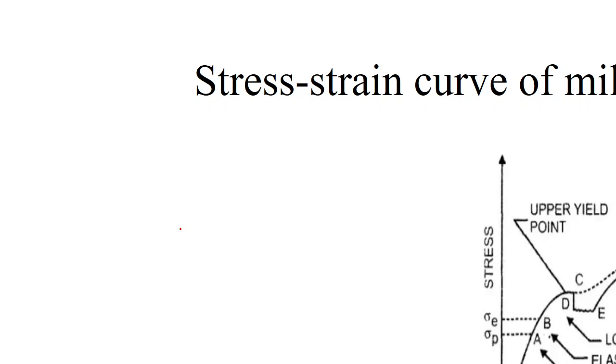Then let's see the stress strain curve of the mild steel material. Mild steel is the most widely used material. First, I am taking a tensile specimen according to the ASTM standard, a dumbbell shaped specimen. Then I am loading it onto the UTM machine and applying a tensile load. This you all know, I will just refresh this concept so that it will be a continuation.